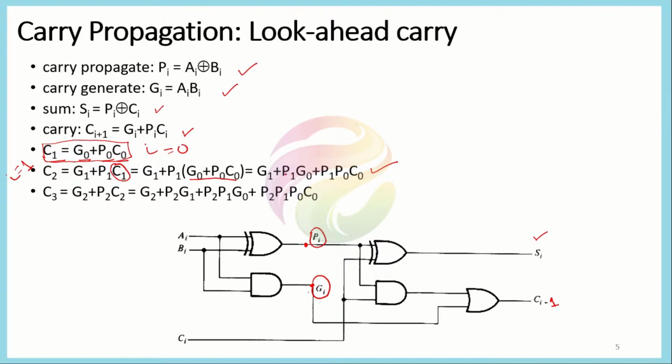So you can see that when we are at level 1, or i equal to 1, it means we are at the second full adder of the cascaded series. And in this, we are no longer dependent upon the C1 term. We are only dependent on the C0 term. Look, it's only the C0 term now, because we have put in the value of C1 here.